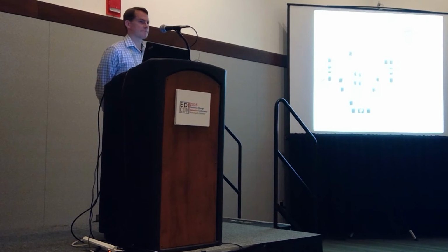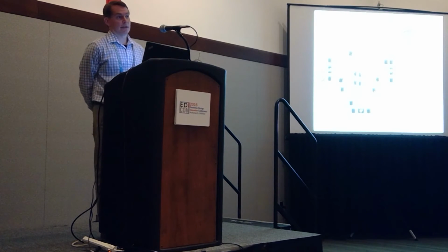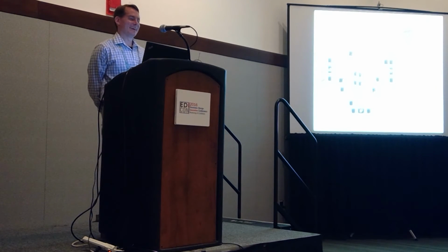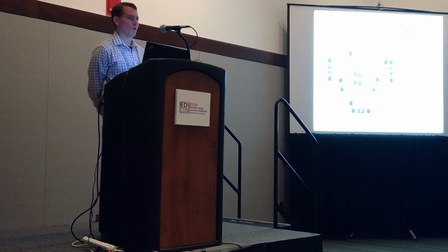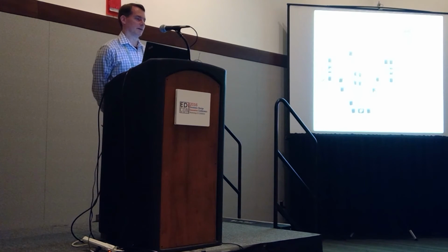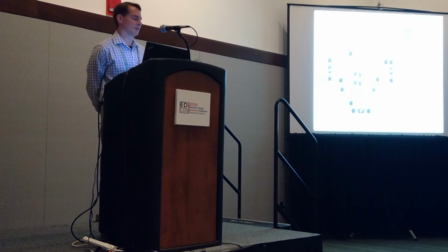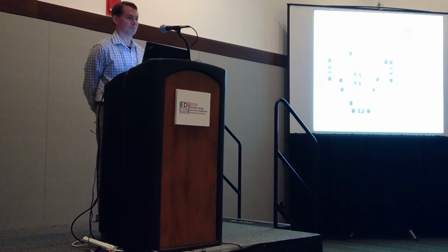What prevents you from going to 30 dBm on a LO drive? In theory, nothing. In reality, our lab equipment. Sorry, that's fair. The current set of lab equipment we have can generate about 1 watt, but as soon as you add a cable and go to higher frequencies, you really lose it. I've used TWTs in the past. We just don't have that kind of equipment right now. If we had the equipment, we could go there.